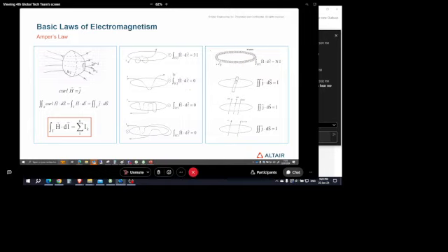And we can follow like these examples. The interesting one here is the torus. If you have a torus and then you have n turns around this torus and you want to compute the magnetic field created there, it's simply Ni. So you can imagine that you cut that and you put that on the stator of the machine for a given phase. Then the magnetic field created by this phase is equal directly to Ni, sorry.